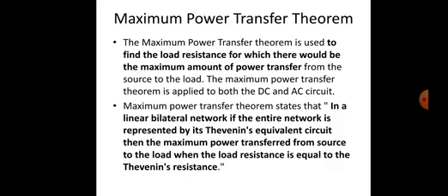Maximum power transfer theorem states that in a linear bilateral network, if the entire network is represented by its Thevenin equivalent circuit, then the maximum power is transferred from source to the load when the load resistance is equal to the Thevenin's resistance.